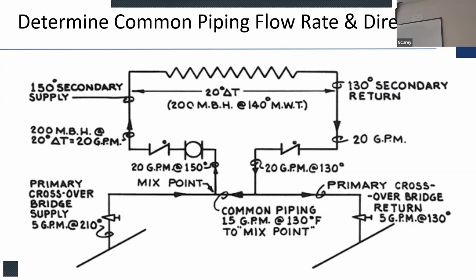I need to provide the design flow for all of these, if I had a bunch of them. And there'll be other pictures that make a little more sense. So if I'm a pump, high pressure, low pressure, the high wants to get to low, I want to cut across this bridge and get right back to the suction of that pump. So I'm going to use that balancing device to throttle down and make sure I have, in theory, 5 gallons a minute. That's what I'm chasing.